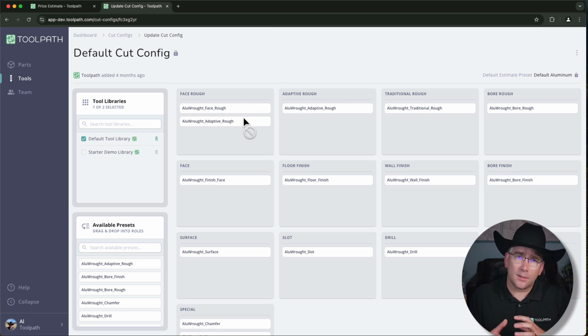But we also need to make sure that tool geometry, that tool itself, is allowed to machine some of that geometry. So as an example, you might have a 2-inch face mill and a 2-inch hole. Well, that tool geometrically could drill a hole, but the tool does not have an acceptable role to do drilling. And so this is where the roles are very important.